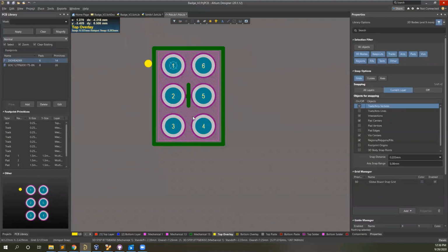So that's it. It's a little annoying to do this. I know, like you might have seen, this video took however long. It's really tedious to make your own parts. It's very annoying. So that's why you should try to use the same parts when you can, and make them right the first time so you don't have to edit them. You can also pull parts off of the internet, but make sure that you check them and then edit them if they're incorrect, because you do not want to have incorrect parts on your board.